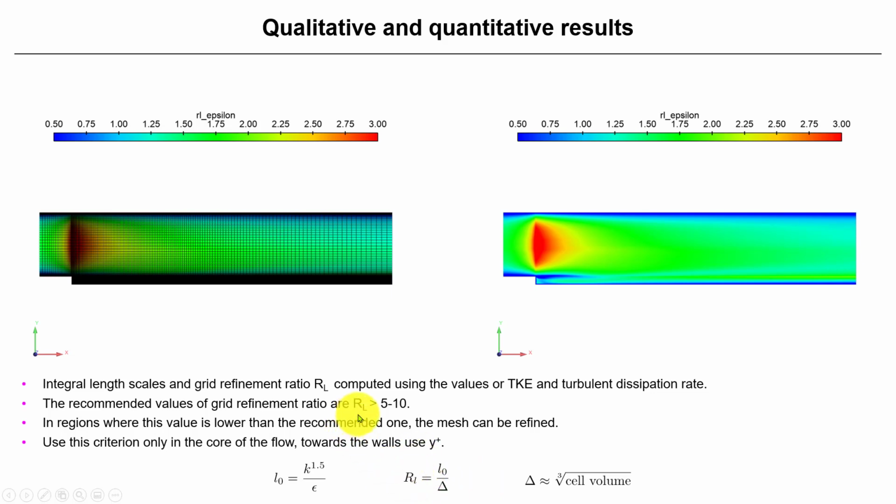Okay, and the minimum for running simulations to get good results, and in the limit for scale-resolving simulations, will be 5, ideally 10. So in this case, we're plotting and see that the value that you have here is something about 2, or probably 2.5, a little bit higher, but it's not good enough. So see here that this metric is already giving you a good reference of where you need to refine the mesh. And as you can see here, you will realize that it's true what it's telling. You see that it's telling you that here you need finer meshes, and see how it's stretched here.